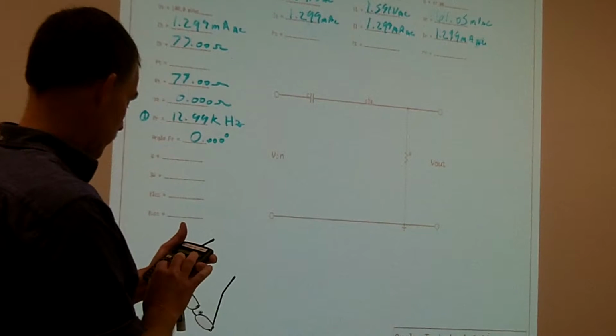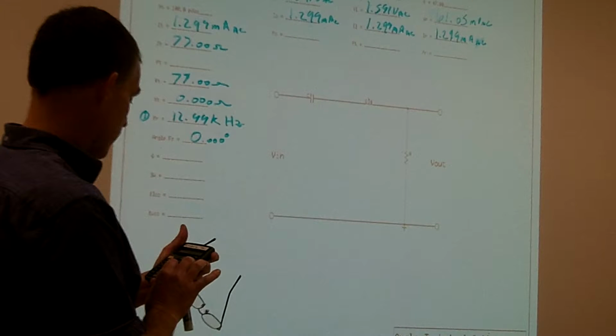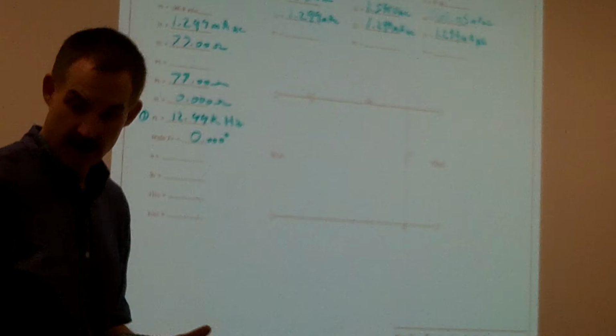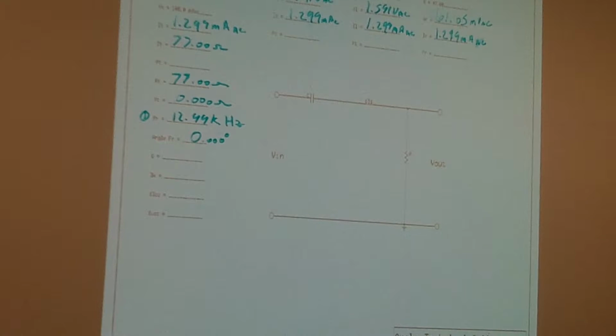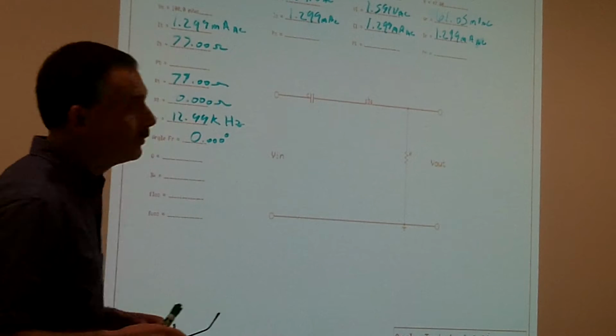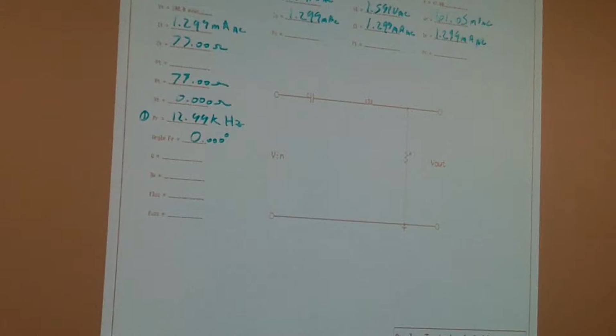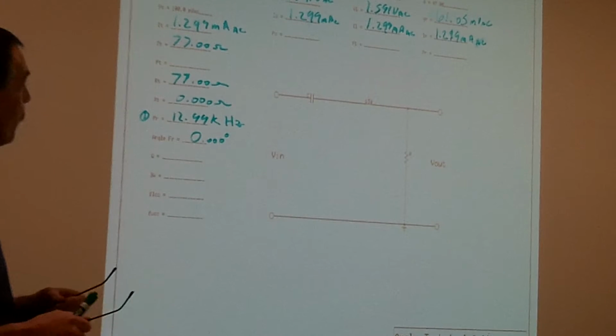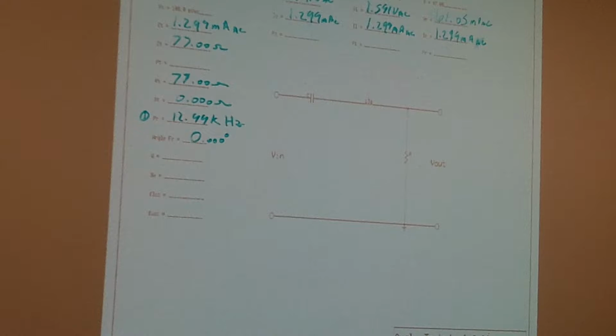1.299 milliamps. Yeah, I'm sticking with Ryan. Well, I must be putting something wrong with my calculator. I'm so not getting it. 47 ohms times 1.299. Oh, I put 229. Oh, jeez. All right, yeah, so you should get 61.05 millivolts AC.